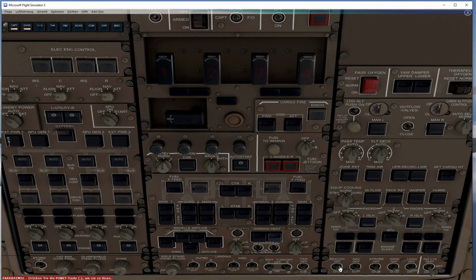And the beacon, or we like to call it the bacon, is the red light on top and on the bottom of the airplane. Well, taxi light, looking straight to the front from the nose gear. Runway turn-off lights are left and right from the center, from the front gear, looking towards the left and to the right. And then we have inboard and outboard landing lights, which are pretty bright. Yeah, these are the switches for the lights here in the cockpit, so during night you can adjust them as you like, and the strobe light switch, them on to fully bright.